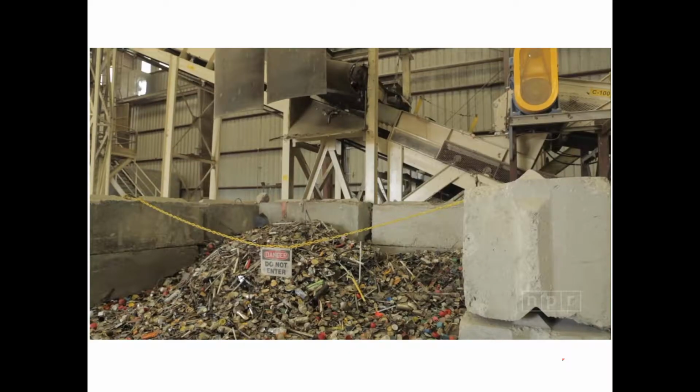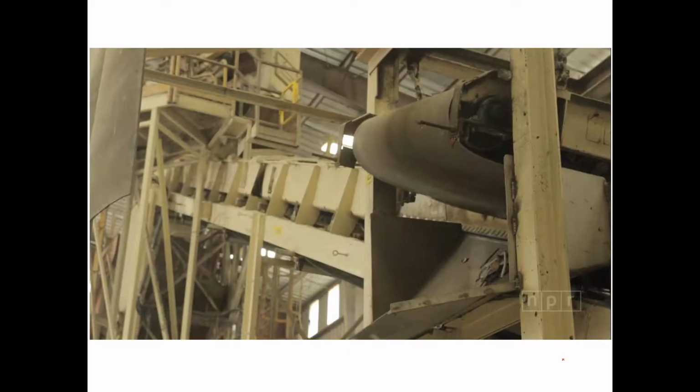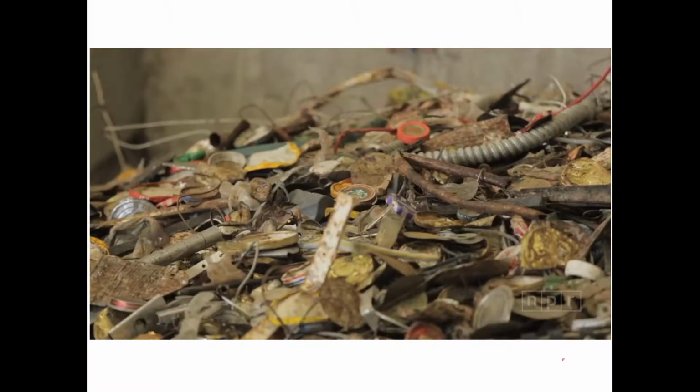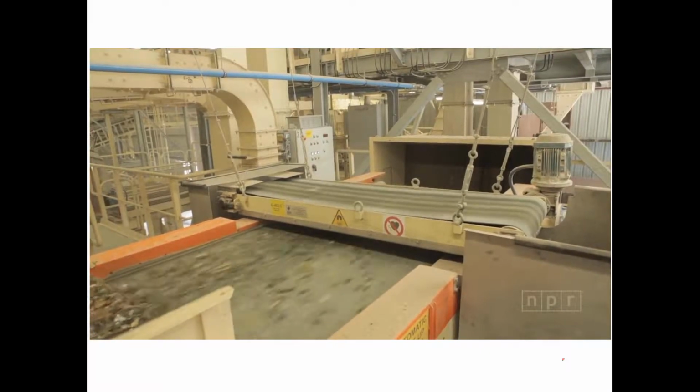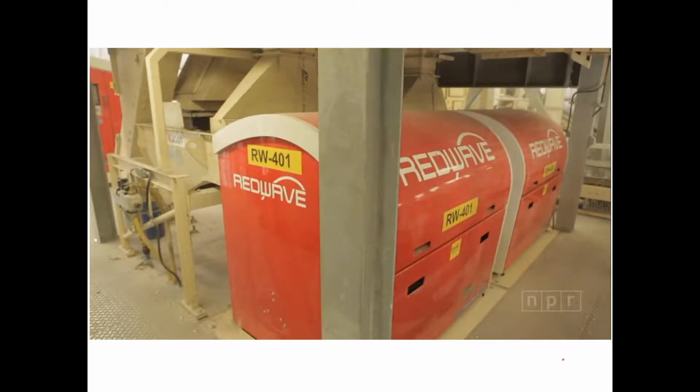The first step is to remove small metal objects that are in there with a magnet. After going through that process, the material will go to an eddy current, essentially a reverse magnet, which will charge any non-ferrous metals in there, aluminum, bits of copper, and so on, with an electric charge, and those non-ferrous metals are then ejected from the stream.